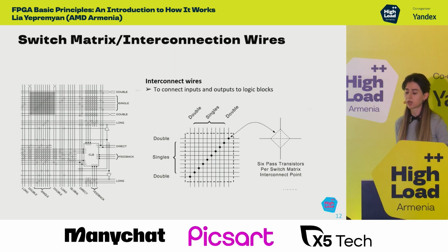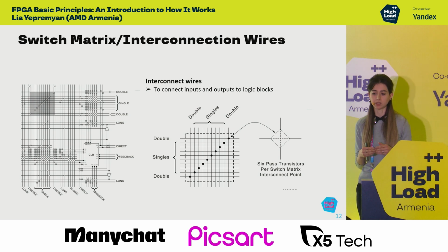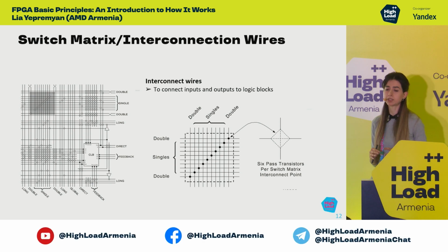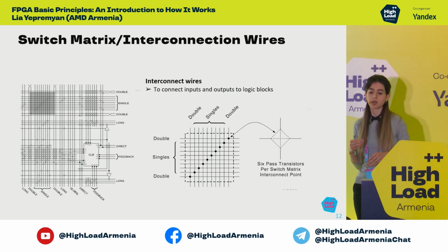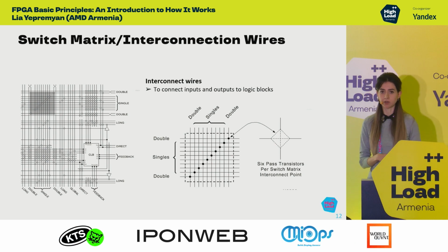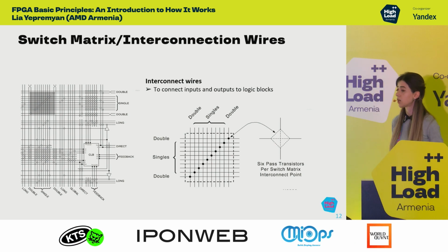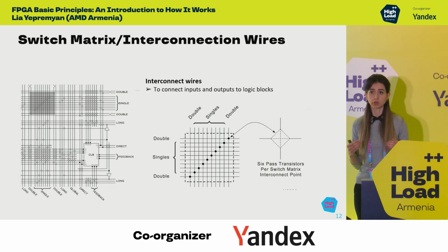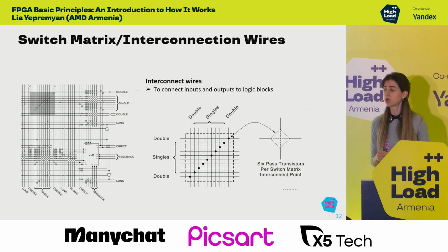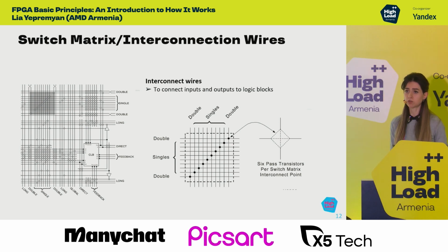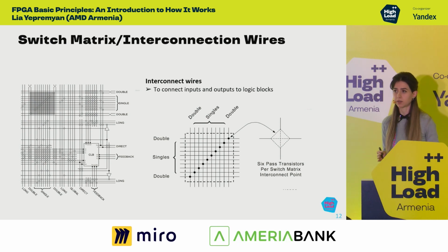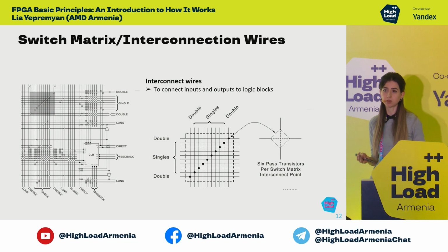Interconnecting routing is used to connect input-output cells with logic cells. Three types of cells are used to provide this connection: three-state buffers, multiplexers, and pass transistors. Pass transistors and multiplexers are used inside the logic cluster to connect logic blocks together, while three-state buffers are used for global routing. For global routing, different types of techniques are used. One can be cellular, pipeline, or island-based.